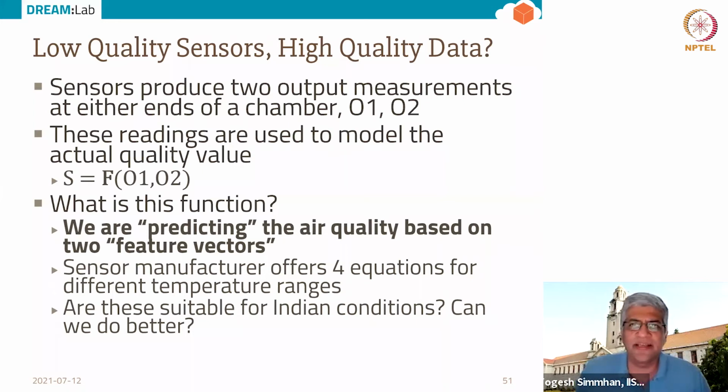So for example, for some of the gas sensors that we have, internally the sensor has two electrodes within a certain chamber that can take in the ambient air, and then it measures the conductance between these two electrodes within the chamber, and that is going to be a function of the density of a particular type of gas within that chamber, right? And this keeps getting sampled periodically, and that is what is reported by the sensor as, let's say, parts per billion of a particular gas, right?